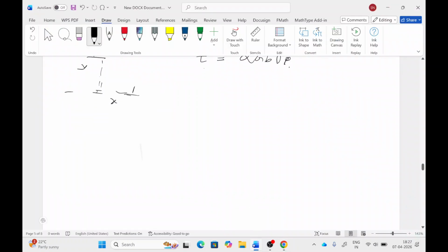Okay, so we'll discuss now how dislocation density increases. We know that dislocation lines are present in the material or in the single crystal. So if this is a dislocation line pinned at 2 points, these 2 points can be grain boundary points or free surfaces. If the material is subjected to a stress coming in this direction, because of this applied stress, the dislocation line length increases.